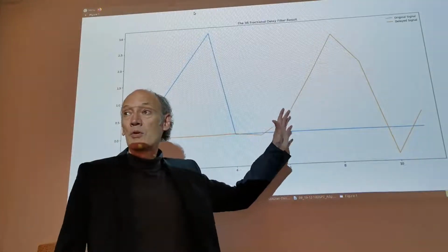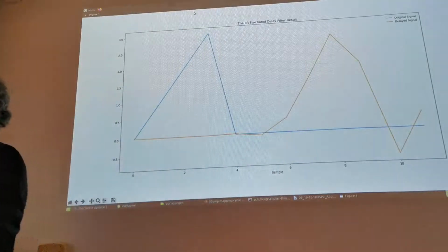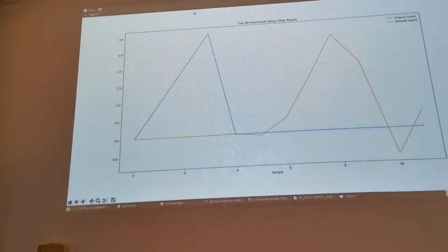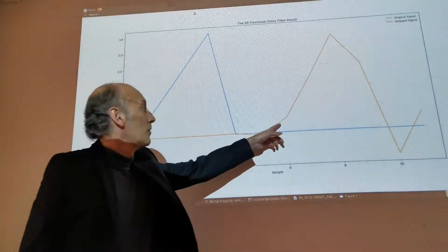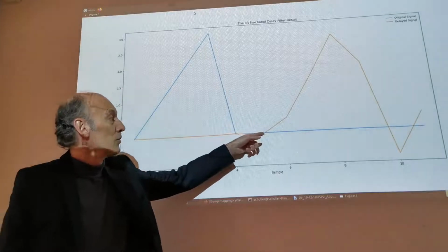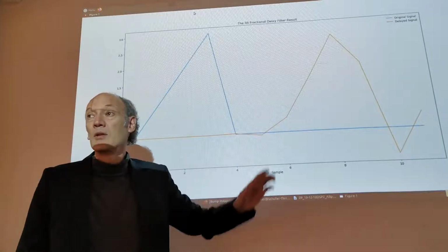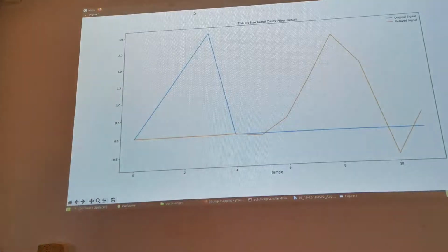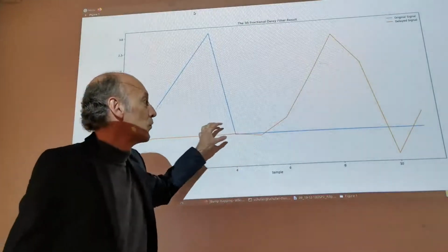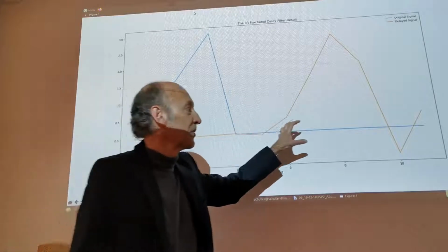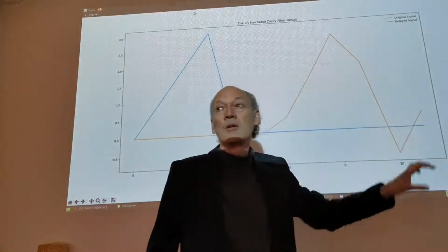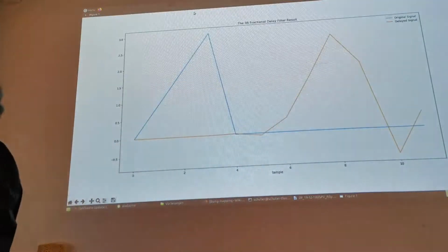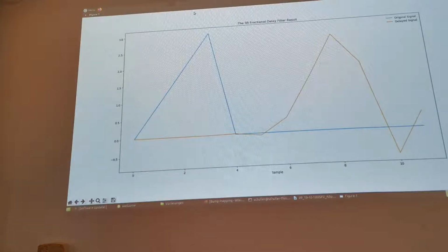If you have audio signals like clicks from a castanet and you want to shift them, then this is good, because this reduced number of ripples in the beginning means we don't have pre-echoes. The ear is very sensitive to artifacts appearing before in the signal, but less sensitive to artifacts which appear behind, because the ear also has this kind of IIR property.